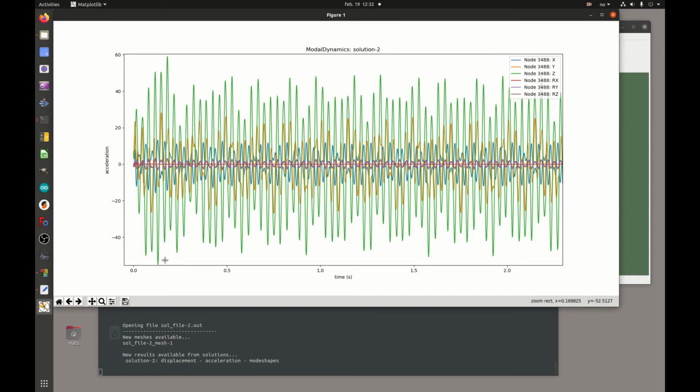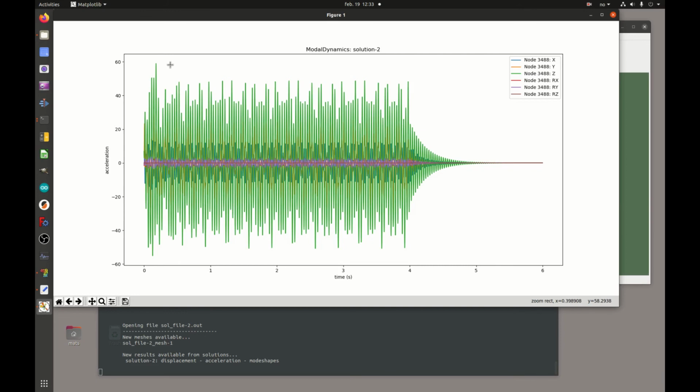There is definitely an increase there. The acceleration is 3 times higher at the dummy mass element, but it doesn't look like we have any serious resonance really. It's being accelerated, and then when the acceleration stops, it just dampens out there.